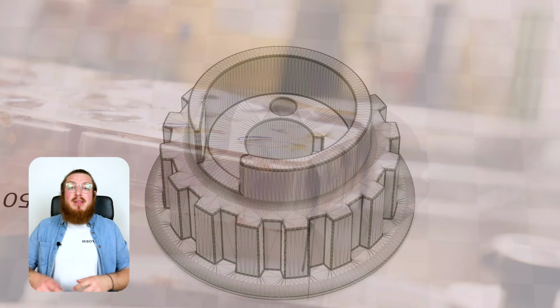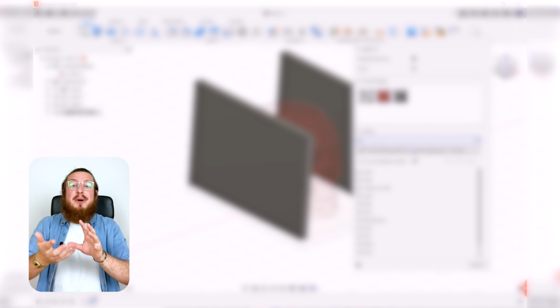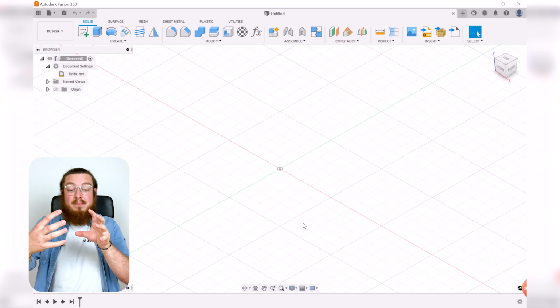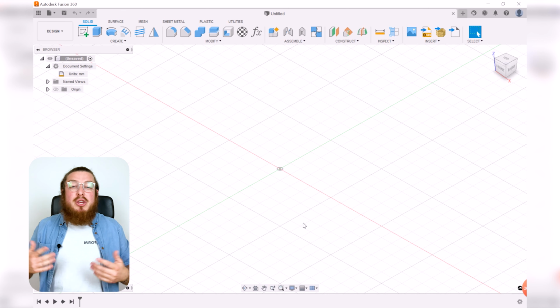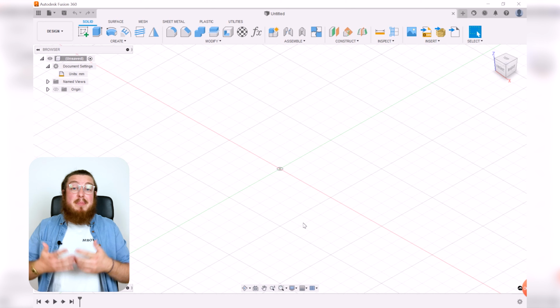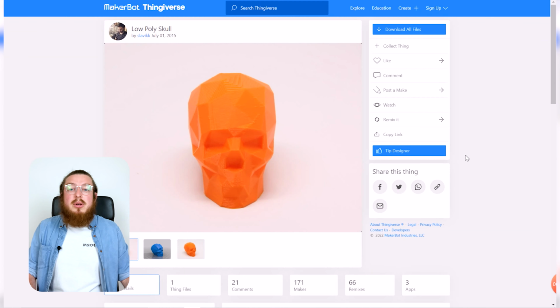So today we're going to be going through a process of downloading an STL from Thingiverse, putting it through the rules so that we can make a little silicone box and then figure out exactly how much volume of silicone we'll actually be needing. Because we're going to be pouring this silicone into something, we're also going to be making a molding box. Usually made out of a very cheap flat material, something like foam core that you can then crack away, and basically it'll be filling up our volume of silicone that we can pour into so you don't get any spills or any leaks.